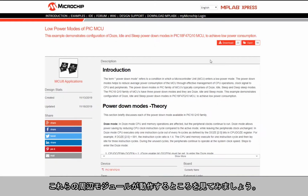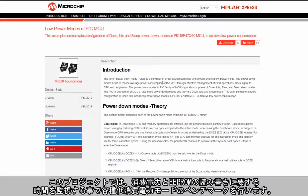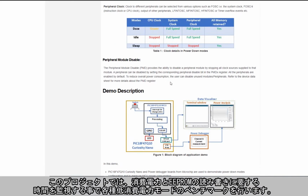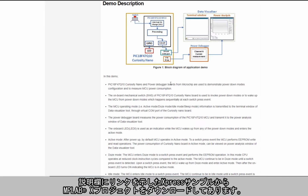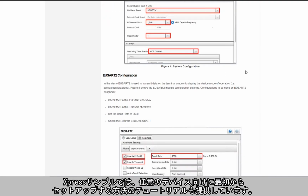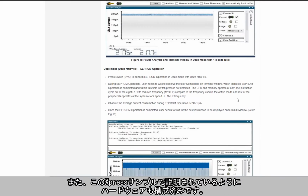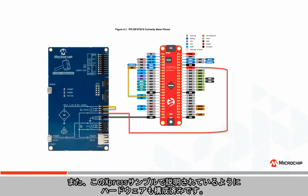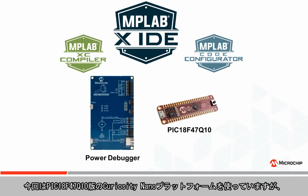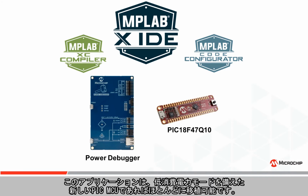Okay, so let's see these bad boys in action. This project is going to allow us to benchmark the different low power modes by monitoring current consumption as well as the length of time for double EEPROM read and write operations. I've gone ahead and downloaded the MPLAB-X project from the express example linked in the description that includes a tutorial on how you go about setting this up for any device from scratch. I've also gone ahead and configured my hardware as outlined in the express example. Just to reiterate, here is the hardware and software I am personally using when I built this project. Although I am using the PIC18F47Q10 variant of the Curiosity Nano platform, this application should be portable to most newer PIC microcontrollers that have the low power modes available.